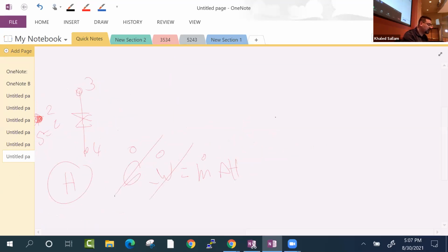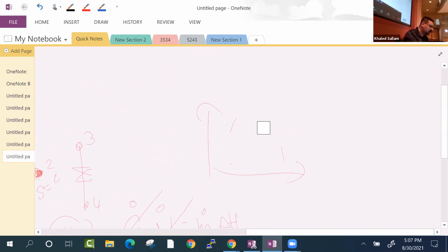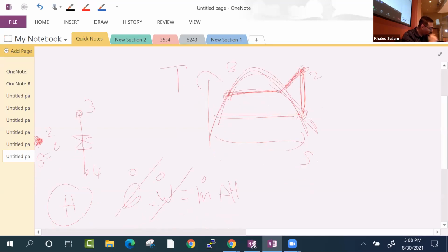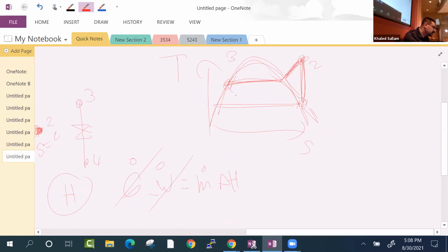Okay, on a T-S diagram, let's make it nicer. On a T-S diagram, this cycle, here is the compressor. The compressor will look up like this, 1 to 2, and then the constant pressure heat rejection at the condenser will take you like this, constant pressure heat rejection, all the way to this. That is 3. And then 3 to 4 going through that throttling device will look like this.